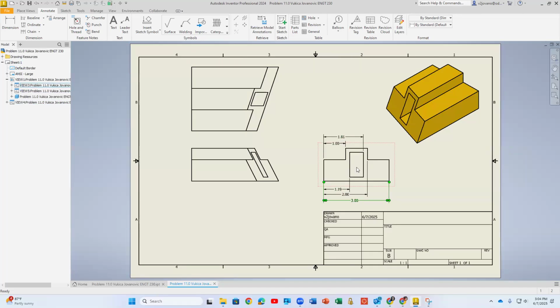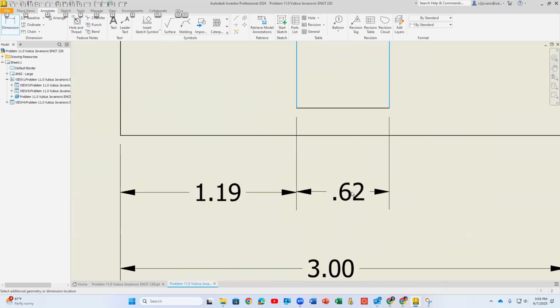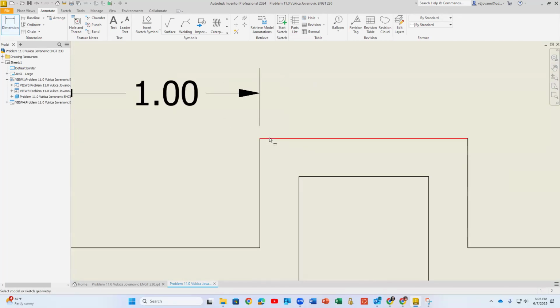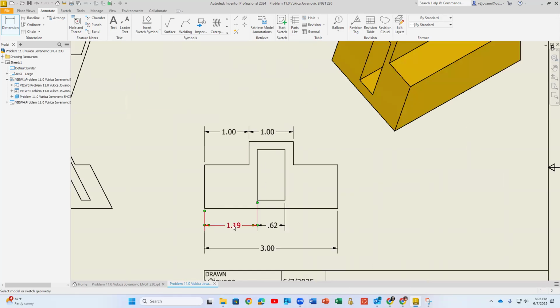And you see, we have here a rectangular shape. So it's better that we dimension it here when we really see the dimensional shape. So maybe this would tell us location. Maybe for the size, it's better that we add how big this is. And try to use Alt or Shift or Control. This is Windows software. I'm using Control, so this will be better aligned. So here, if I zoom in and maybe again Shift, it will be more in line with the other one. Because for a rectangular shape, it's better just to have location.